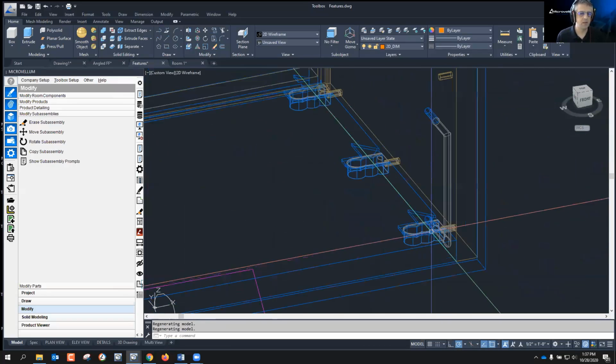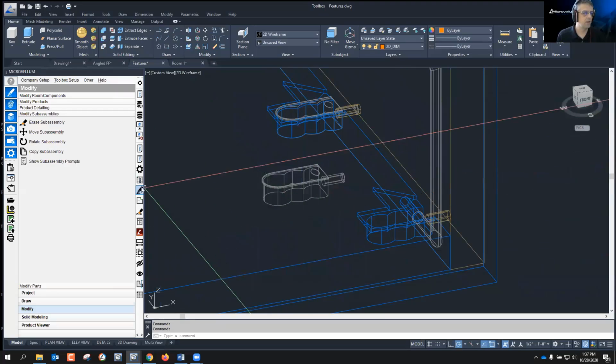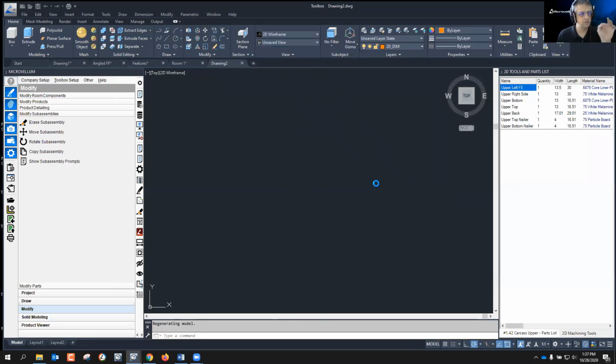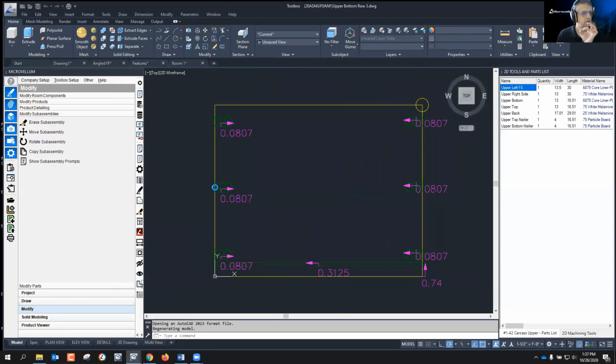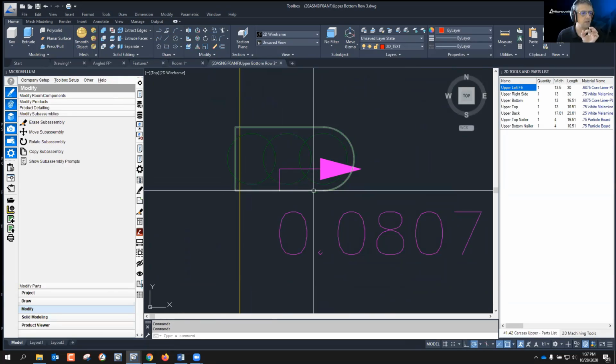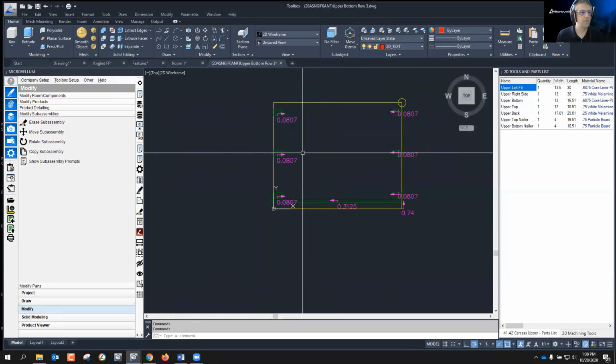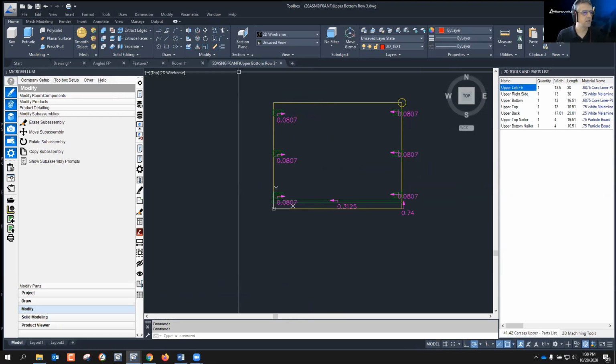The 3D rep is a little funky, but if you take a look at the block, here's what it looks like. And if we machine that part out, it is 3 drills. So you'll see it here. See that? We have 3 drills and then a relief cut, a little polyline. So wherever that piece of hardware goes, there it does the machining.